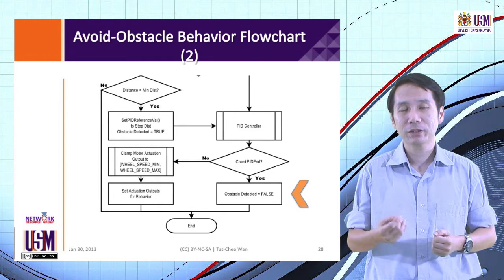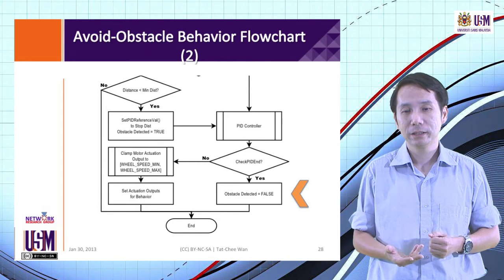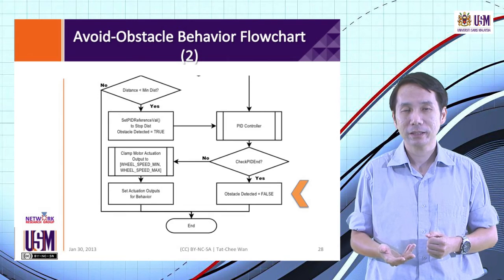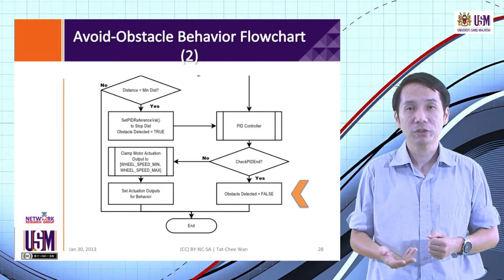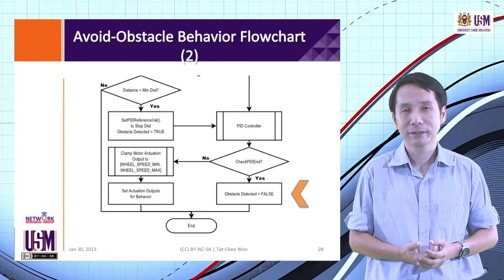Now, when the PID controller has reached convergence, meaning that the check PID end returns a yes, then we would set the obstacle detected variable to false to indicate that we have completed the PID convergence process.